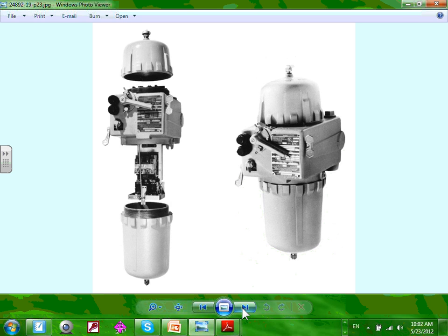So what would that give you guys an idea? Move your control and power distribution equipment away from explosion proof, because you're going to be in a class 1 div 1 location, and you're going to end up with very expensive equipment price wise and very expensive installation for this equipment. If you can't, the industry will be more than happy to sell you a lot of equipment.